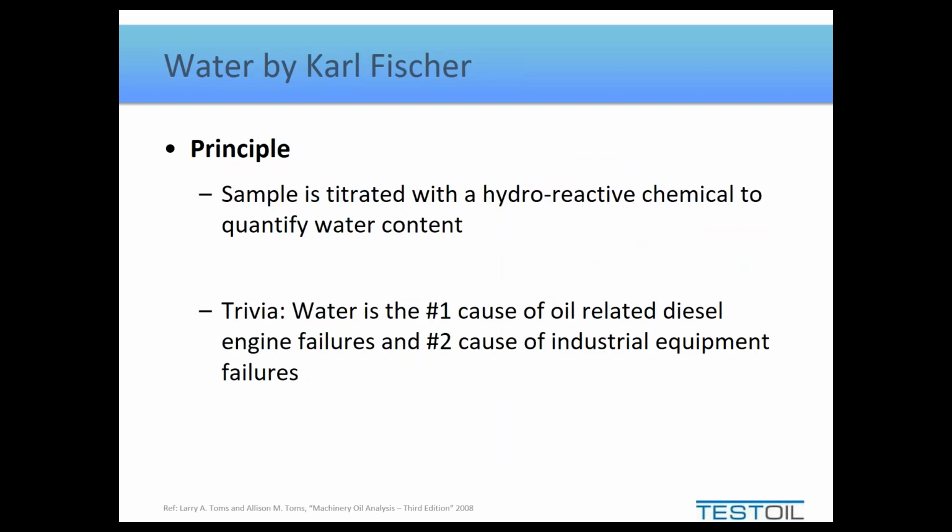The other method for measuring water is, again, a titration, much like acid number. All we do is we use a hydroreactive chemical and we measure how much of that we need to neutralize all the water in the sample. It tells us how much water content is there. Now, just some neat trivia for you in terms of problems. Water is the number one cause for diesel engine oil related failures, and it's the number two cause in industrial applications.